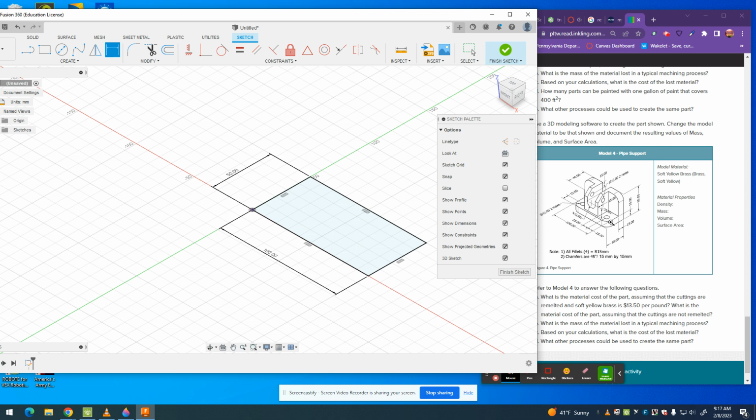The other thing that we can see is that there are actual corners. There are fillets, right, where these rounded corners are. And if I look at the fillet note at the bottom, it says all fillets, so 1, 2, 3, 4, are the radius of 15 millimeters. So for this bottom one, I'm actually going to fillet it in the drawing. I'm going to click here, and click here on those corners. And then I'm going to hit enter, and that should allow me to double click on the number.